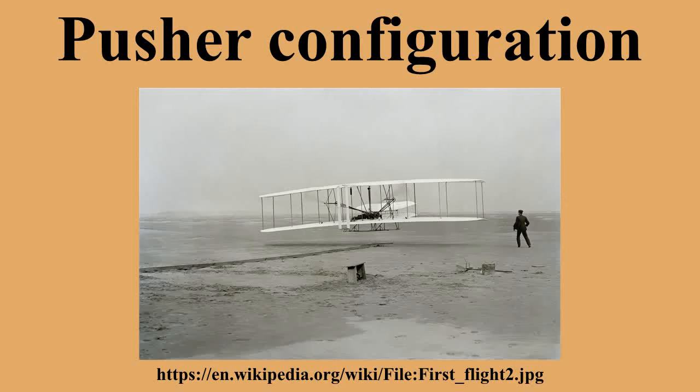The main difficulty with this type of pusher design was attaching the tail. This needed to be in the same general location as on a tractor aircraft, but its support structure had to avoid the propeller. The earliest examples of pushers relied on a canard, but this has serious aerodynamic implications that the early designers were unable to resolve. Typically, mounting the tail was done with a complex wire-braced framework that created a lot of drag.